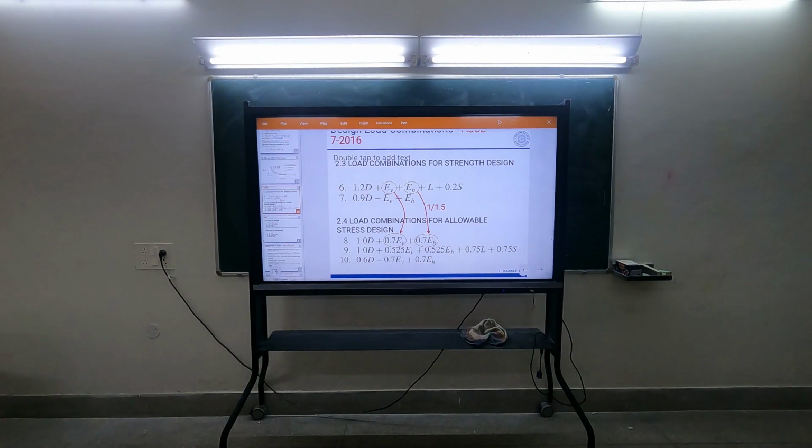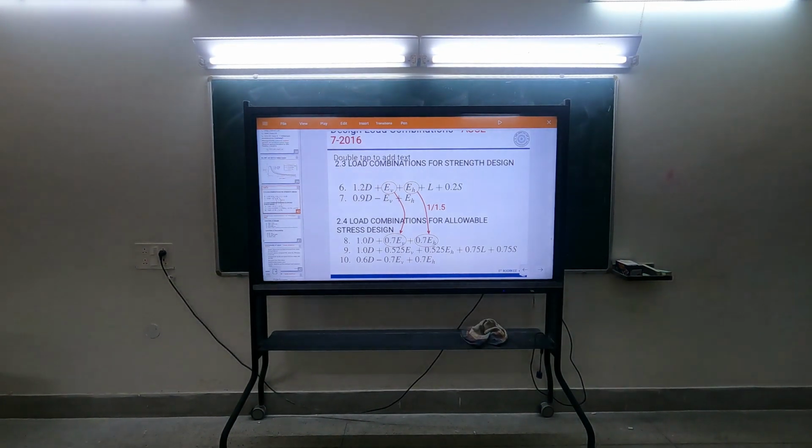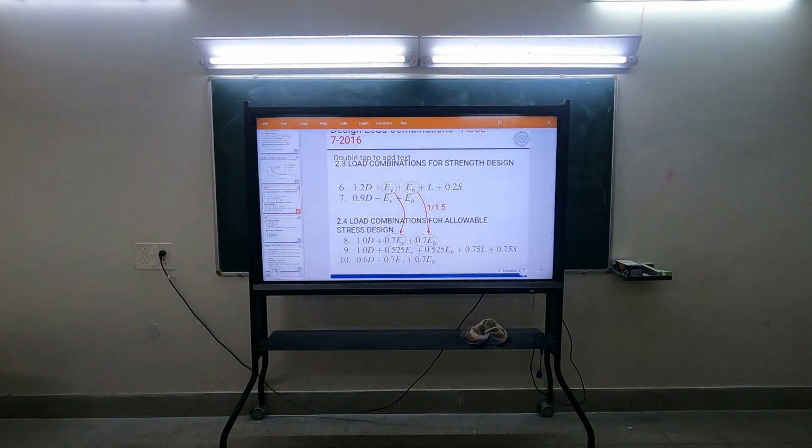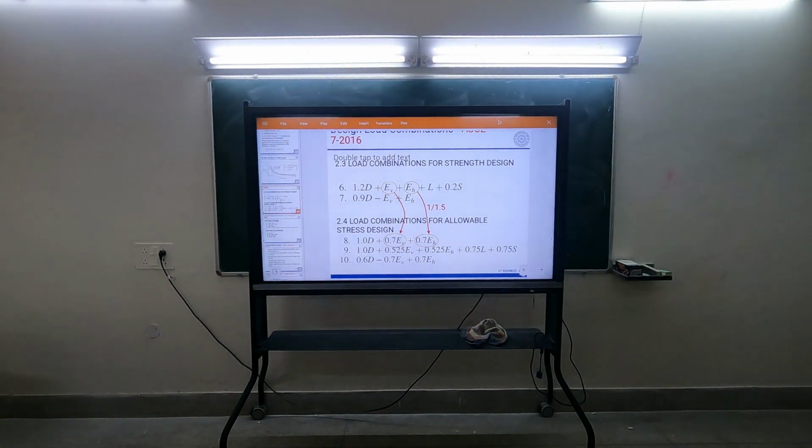So we design for 95% confidence strength, which we call characteristic strength. 95% confidence mean, not more than 5% of samples should have a strength lower than that. But if you test 100 cubes, what will be the average strength? Mean plus 1.64 sigma, because that's how you are calculating 95% confidence strength.